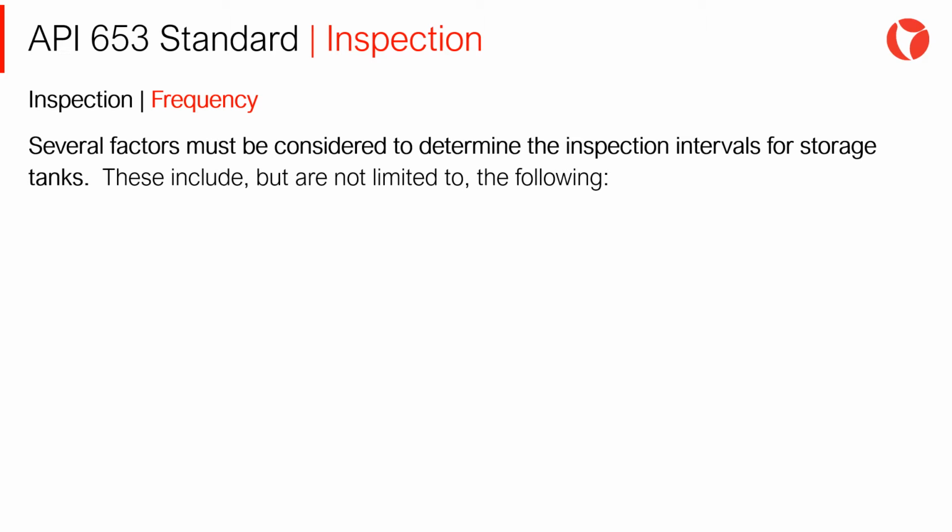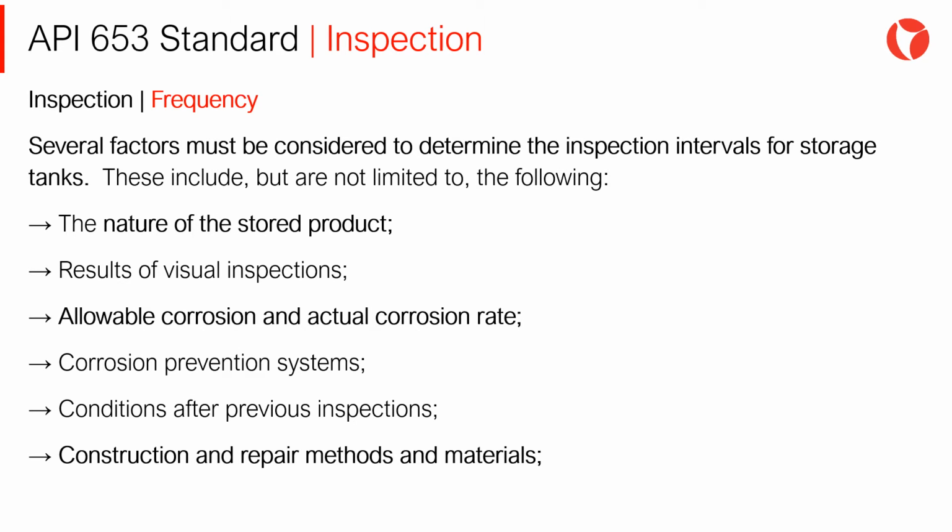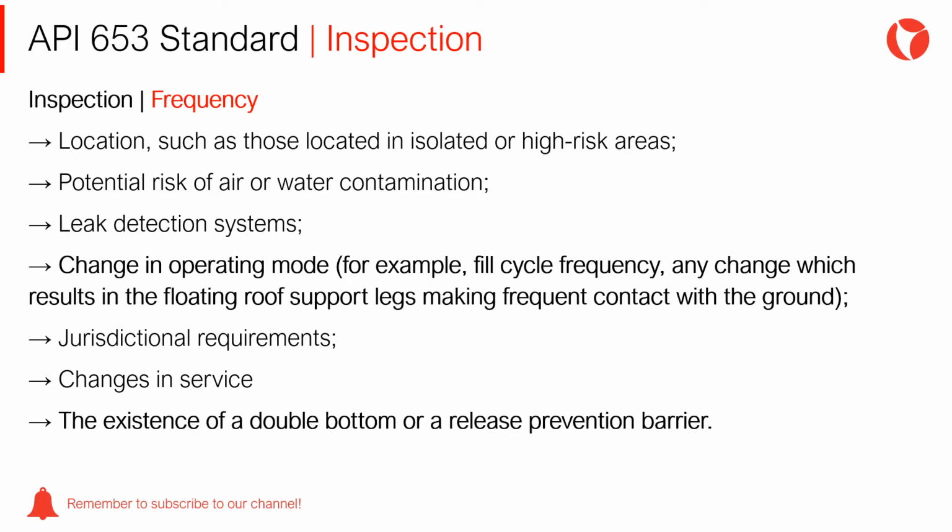These include, but are not limited to, the following: the nature of the stored product, allowable corrosion and actual corrosion rate, corrosion prevention systems, construction and repair methods and materials, leak detection systems, change in operating mode, for example, filling cycle frequency, any change which results in the floating roof support legs making frequent contact with the ground, the existence of double or release prevention barriers, etc.